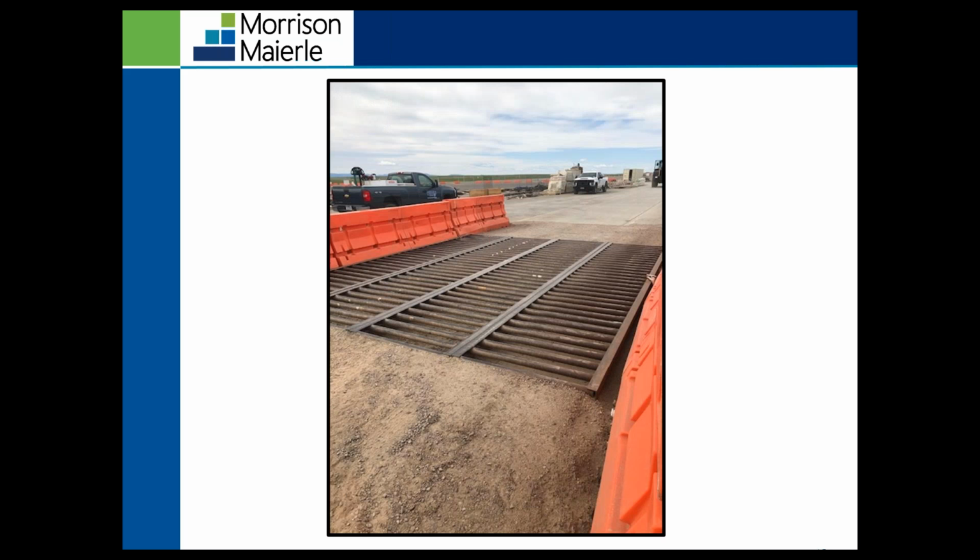The next couple of photos I have here are trackout devices. If construction sites are unprotected at the access, sediment can be tracked onto roads, which, you know, neighbors and the public can see. Those pollutants can then be carried into any type of inlet protection where they can then discharge into a water body.